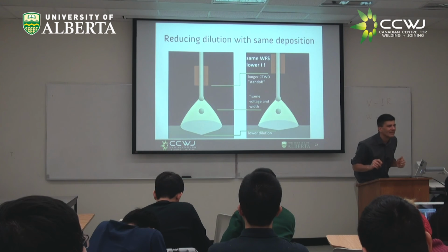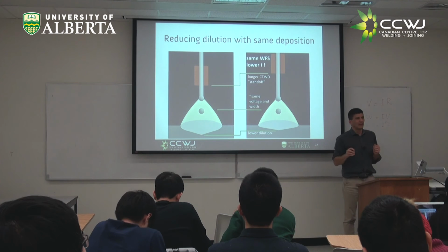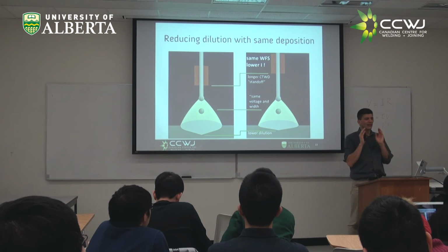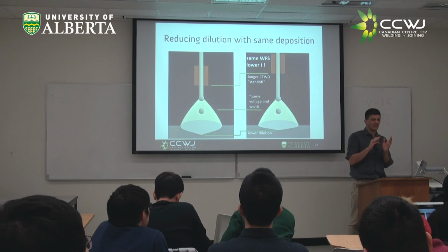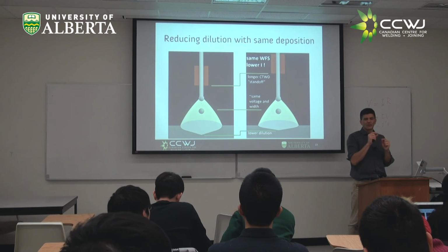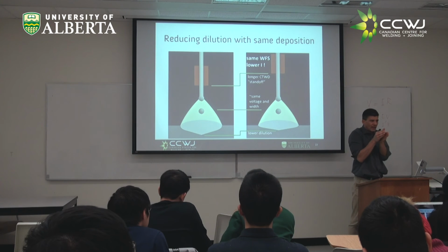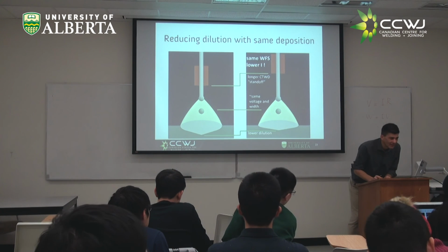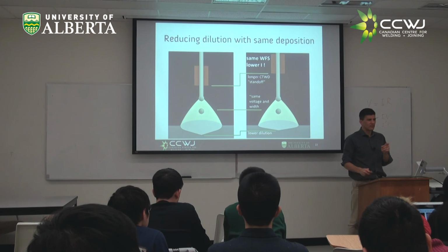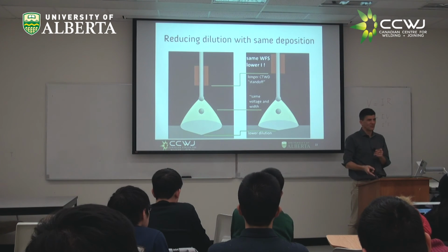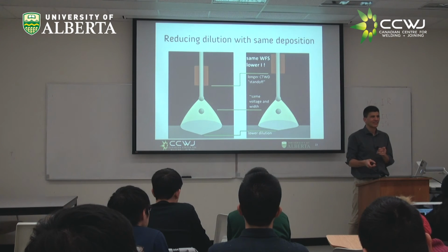Less arc length? Less arc length. OK, let's think together. You say less arc length, like you lower the voltage, right? The current would increase, but you have this narrow track. That's also a problem, yeah. Increase the wire speed. Okay, but if you increase the wire feed speed, it increases the current, which increases your dilution, your penetration. You decrease current, increase voltage.